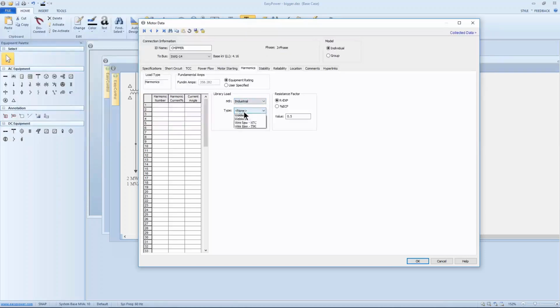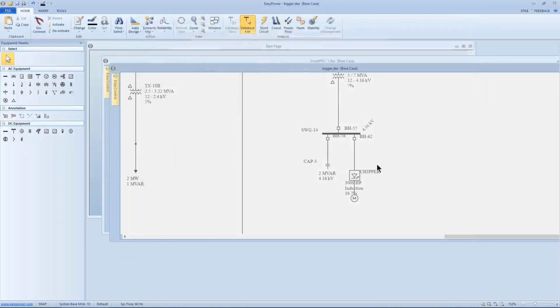We're going to say this is a typical industrial application of a pulse width modulated system at 65% load. Just looking at these numbers, we can tell we're going to potentially have an issue at the fifth harmonic because the harmonic current contribution is so high coming from this type of controller.